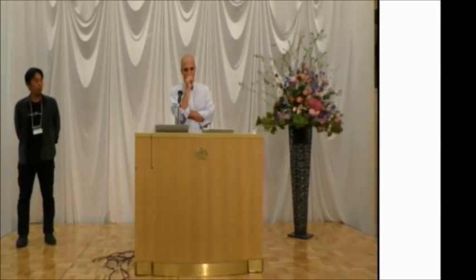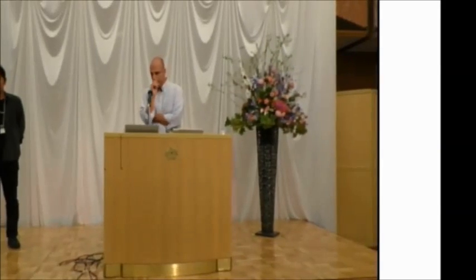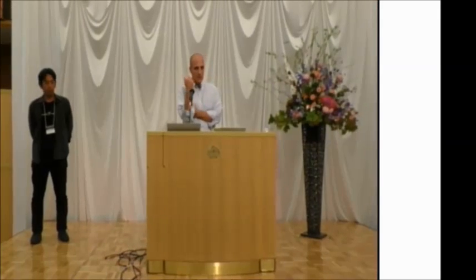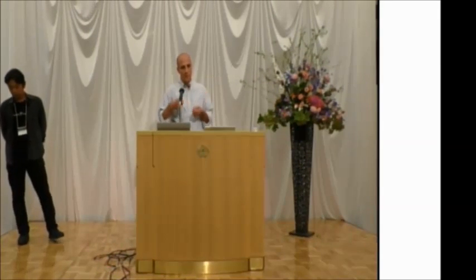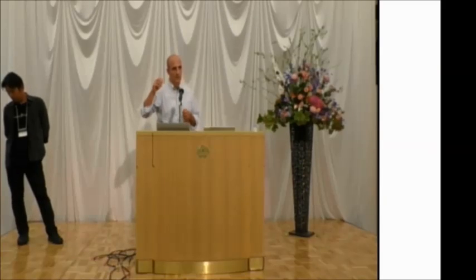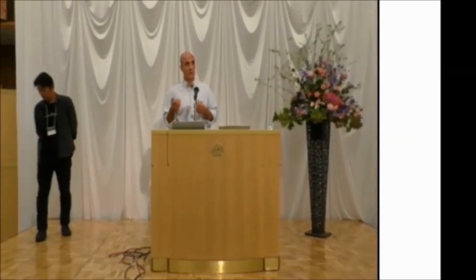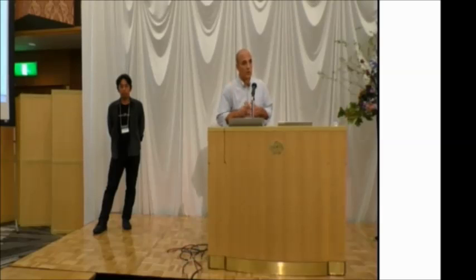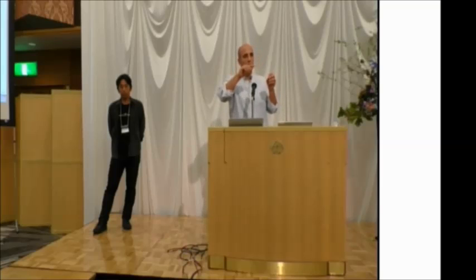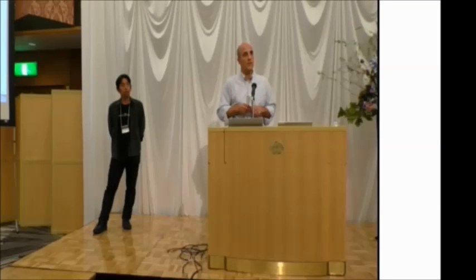I will try to answer your question. But, as I showed you before, the ratio between the velocity of propagation of the bed wave and the sorting waves can be greater or smaller than 1. It depends on the choice that you make for the active layer thickness. But if you want to predict, say, bed dune evolution, this is not the correct model for doing that, because you cannot get this information with this model.